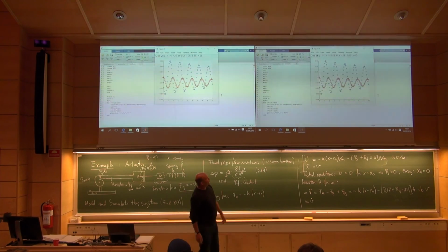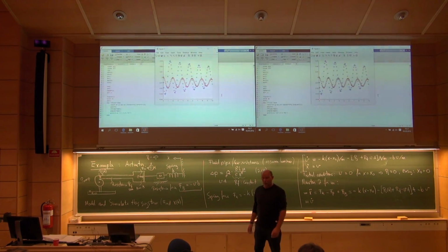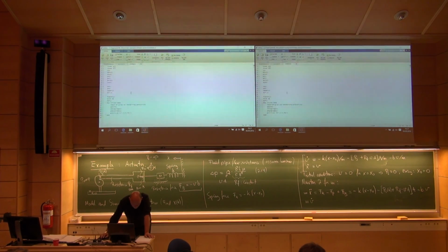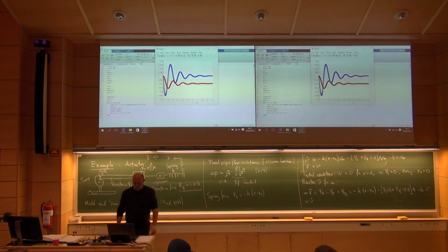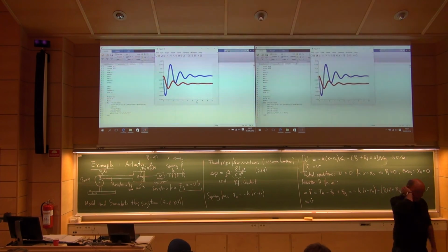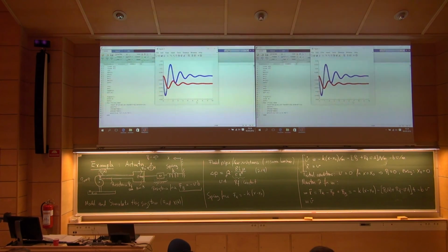If you look at the scale, 0.03, 0.04 on the y-axis, we put everything down here. So now it's a question: should we believe this one or what? One way we can test: use a smaller delta t, and then see, will this change the solution? Oh yes, it did. A lot. So finding a proper delta t will, for us, involve a little bit of trial and error. So this one, yeah, we can believe it. It's not much displacement, but if you put meters and seconds and units for all our parameters, it's moving 2.5 centimeters back and forth here.